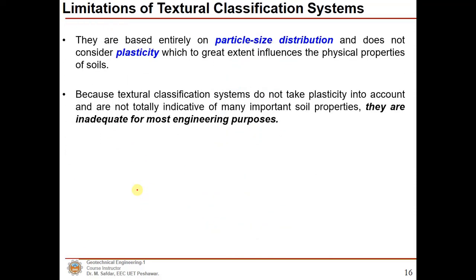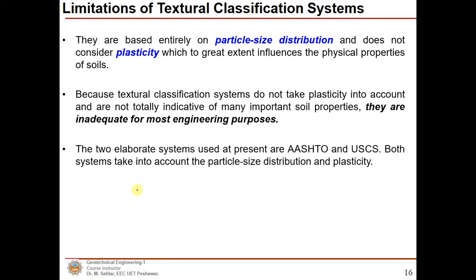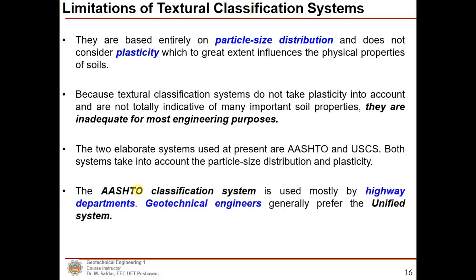We discussed the limitation, that only particle size distribution is considered. However, plasticity, which is very important in changing the physical properties of the soil, such as the compressibility or the settlement behavior of the soil, is greatly dependent upon the plasticity of the soils.